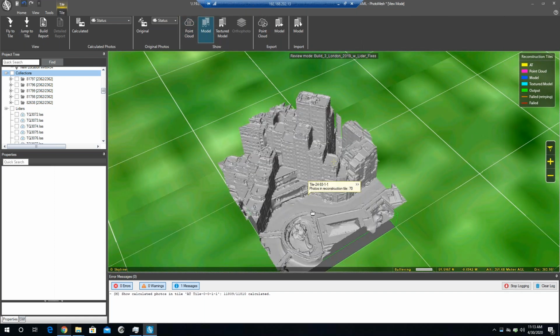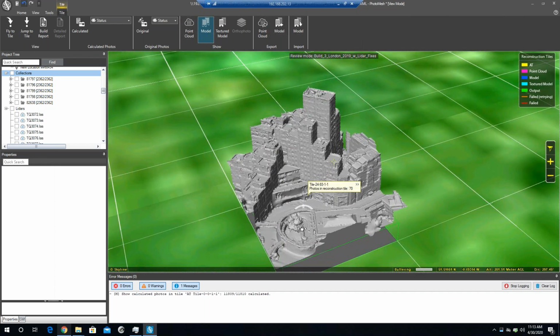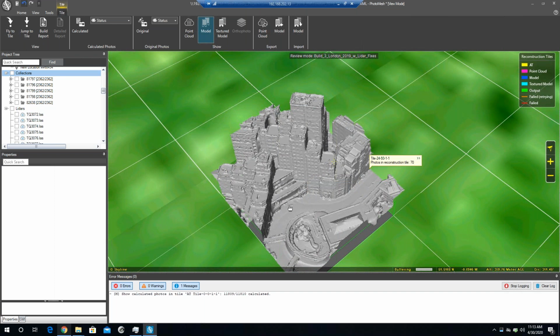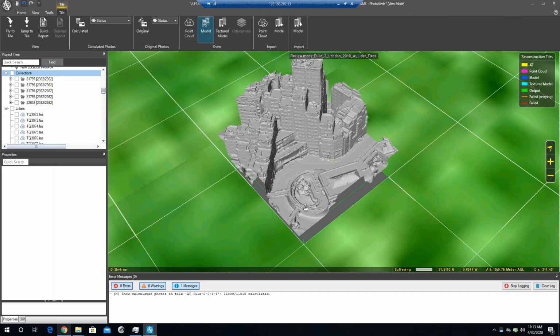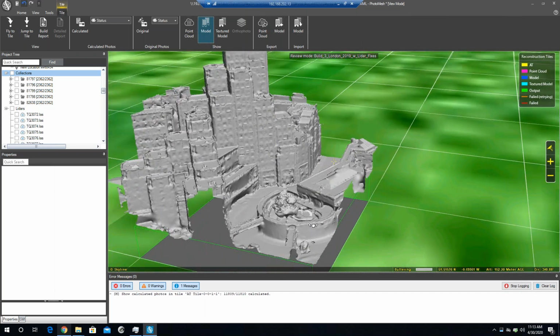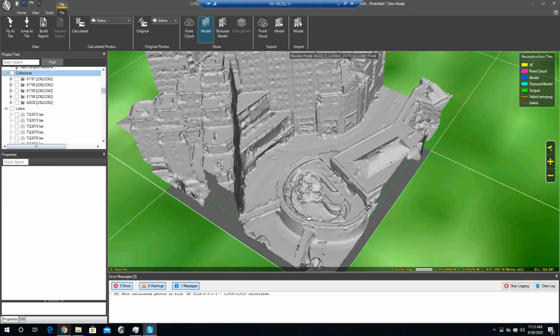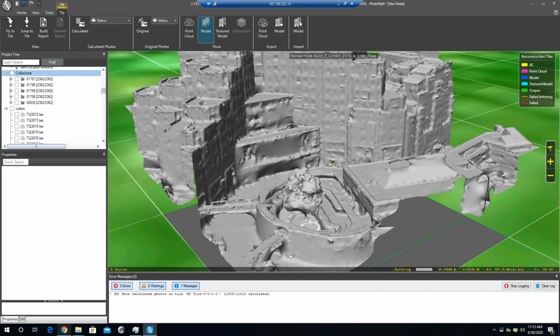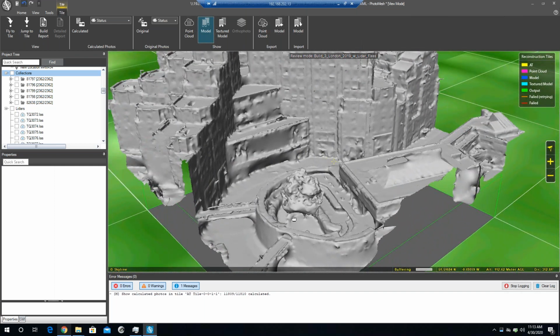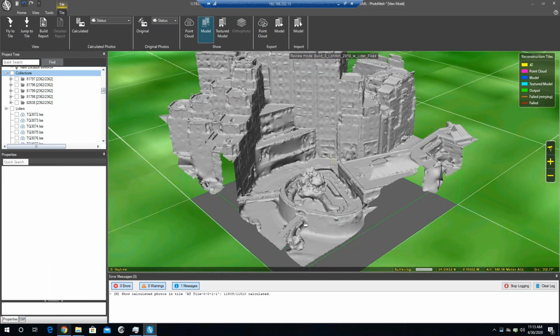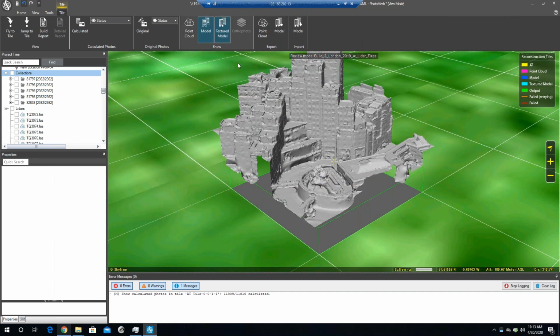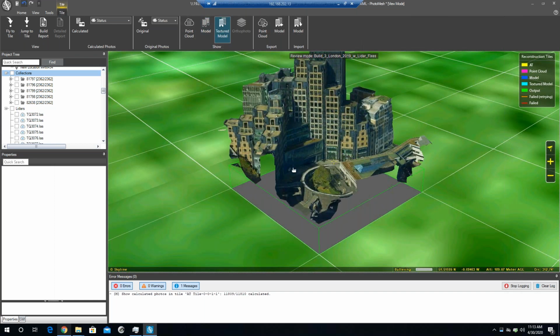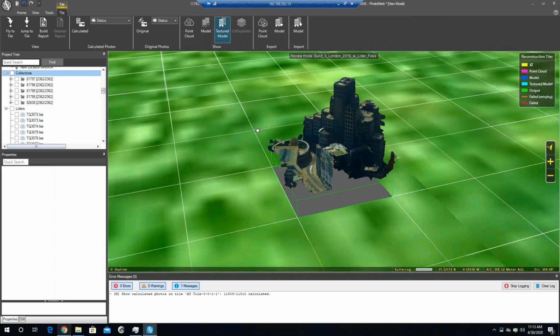The mesh model is the geometric surface that gets generated from the images, which is a full 3D surface. So whatever is able to be viewed underneath, which LiDAR a lot of the time does with vegetation. So trees will be correlated below the tree using the LiDAR points. As you can see in this example, the area over here was not correlated from the images. It was supplemented from the LiDAR points. And then the textured model, which we can see of a single tile.